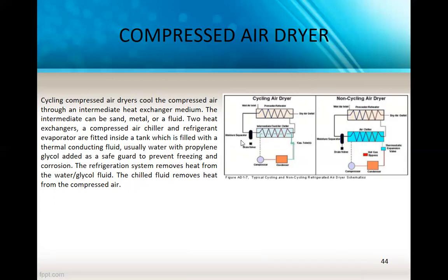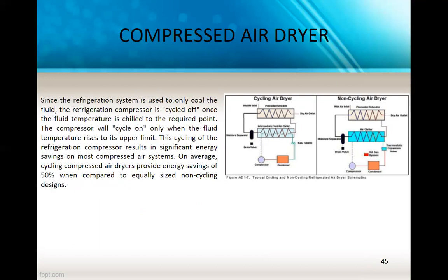There's a storage and cycling. Since the refrigeration system is used to only cool the fluid, the refrigeration compressor is cycled off once the fluid temperature is chilled to the required point. The compressor will cycle on only when the fluid temperature rises to its upper limit.